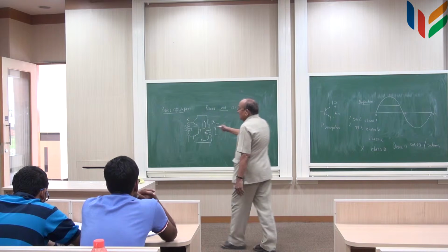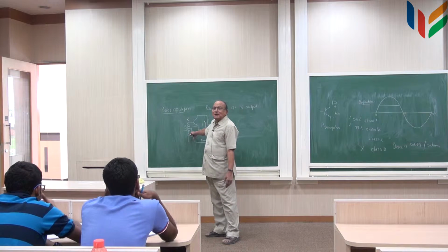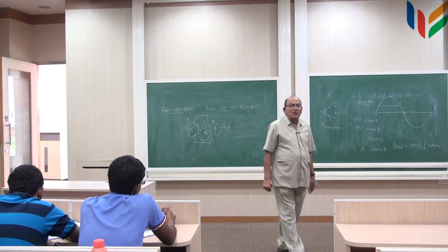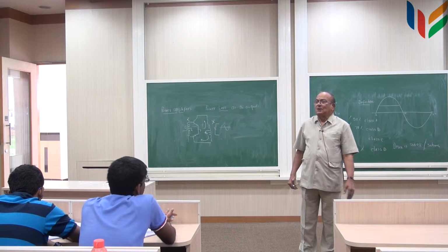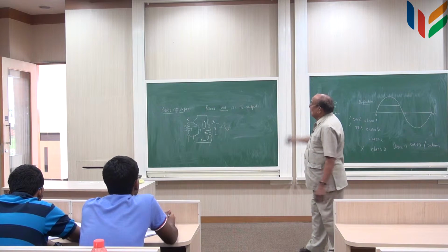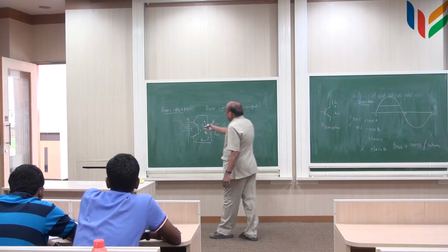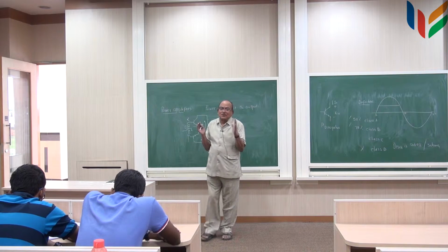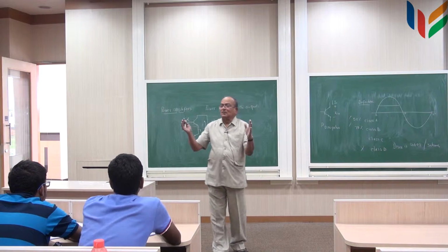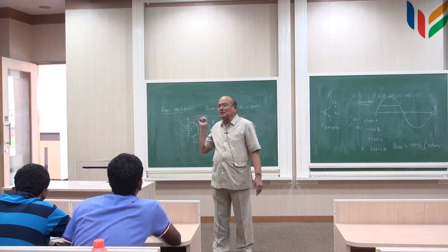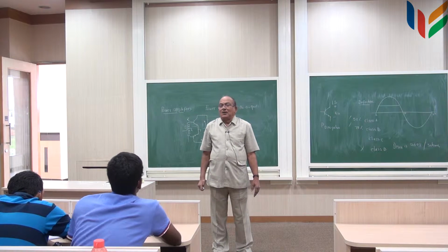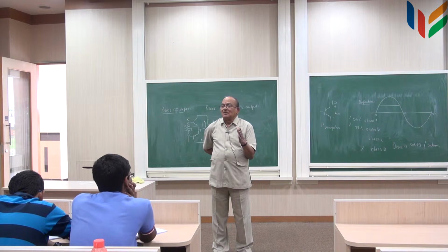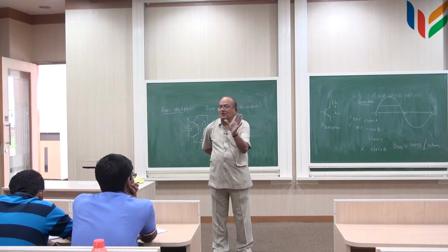So if the signal contains DC or very low frequencies, the transformation ratio is almost 0. So as a result of that, we don't have low frequencies for cutoff and only high frequencies you can do it. But if you go to very high frequency, then all kinds of stray capacitance will come into picture. So there is another problem. So some bandwidth between something like about 50 hertz to about 10 kilohertz was all that we could get using the transformers. 50 hertz is a very bad cutoff frequency for music, because most of the tabla and all this fall in that region.